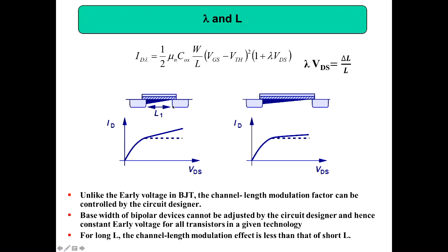Why I have shown this is I have deliberately put this graph. Because now your process technology is reducing, like 28 nanometer in 2014. Now you have got 12 nanometer technology. Then in 2019, maybe 2020, you are going to get maybe 8 nanometer or 7 nanometer technology. This L is actually the length of the channel. This is called the process technology. So when your process technology is reducing, coming down, your channel length modulation is actually increasing.